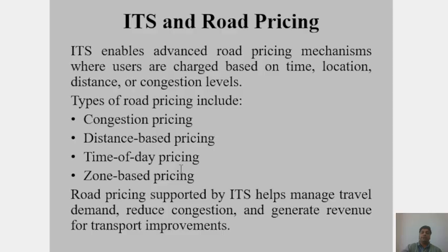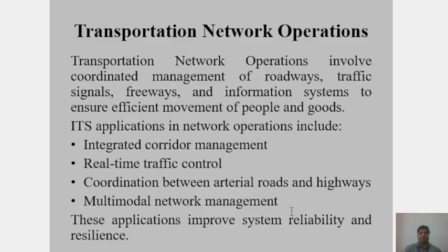Time-of-day pricing depends on what time and in which zone we are traveling. So we have to pay a different type of road pricing. It is supported by ITS, which manages the travel demand. Based on the demand of travel on the road, we can set pricing which can reduce congestion and generate additional revenue for transportation improvements.